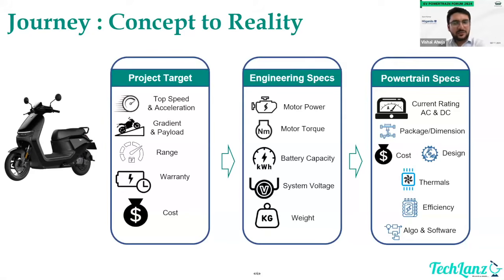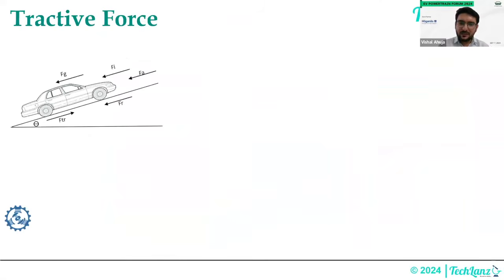And one thing Mr. Amitabh Saran said that people may overlook is the algorithm and software. This is also very important. What kind of functions you are expecting your motor controller to solve as a complete system? What kind of algorithm? For example, for L5 applications, most of the time they don't use a VCU. The VCU functionalities are embedded in the motor controller itself. So you have to give these kinds of inputs also.